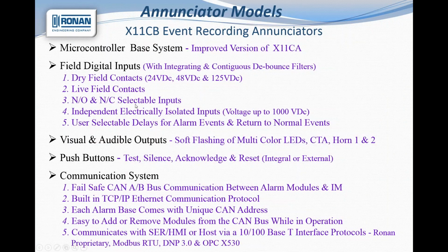The new and improved Annunciator is the X11CB, which is microcontroller processed, so computer driven. We use the same inputs from the field devices: dry, field, live, normally open, normally closed, independent isolated inputs, or other selectable delays. It has the same visual and audio outputs, same push buttons to silence, to test, or acknowledge and reset.